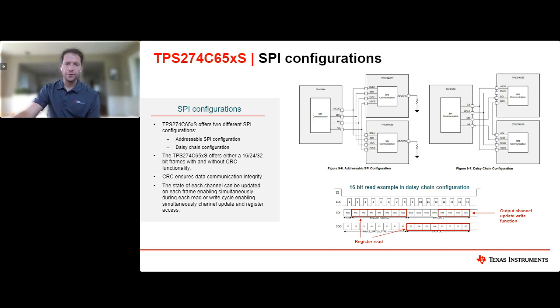One of the other cool features this device has is in each SPI frame, you can actually simultaneously update the switch state. So you can also read from a register as well as write to a register and simultaneously update the switch state. So instead of needing 2 SPI writes or SPI reads to do this, you can do it in just one.